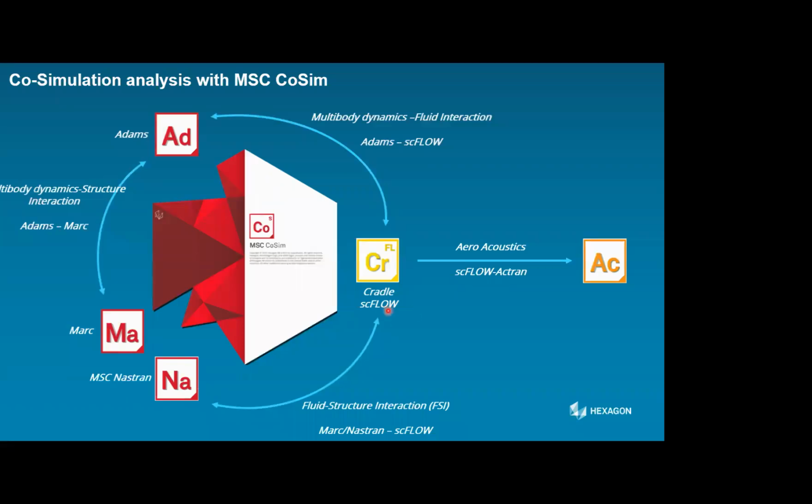Obviously, when a transient analysis is done, and not only transient actually, there is always the chance to also perform an acoustic simulation. So we can perform the so-called aeroacoustic simulation. And this is another very important aspect in e-motor development, since electric vehicles are much more silent than combustion engine ones, so we need to reduce the noise as much as possible.